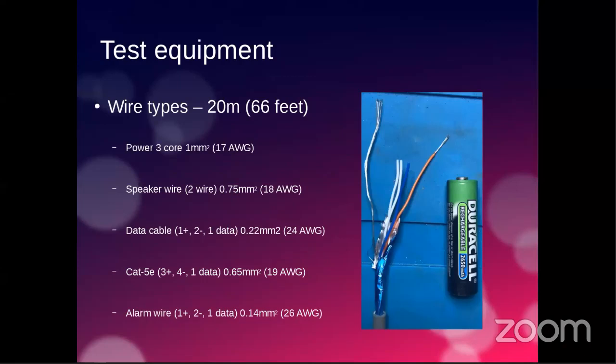Now, there was a case of flickering I was suffering with for a while, and I was using the pre-made T's, and it was a 3-core T. And what I wasn't doing is pulling the data pin out of the place where the power was coming in at the base of the T. And because that data pin was connected, it was picking up a lot of noise, just like an antenna. Right. And once I pulled that pin, that flickering went away. And that one took me forever to figure out.